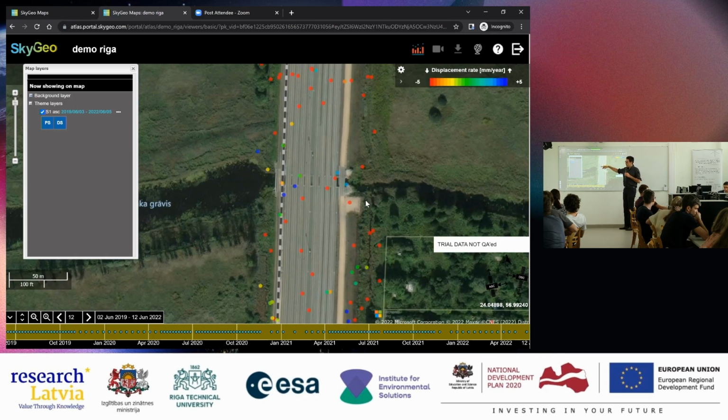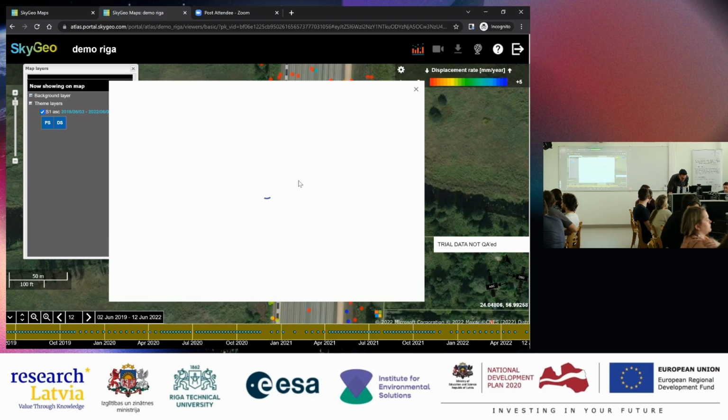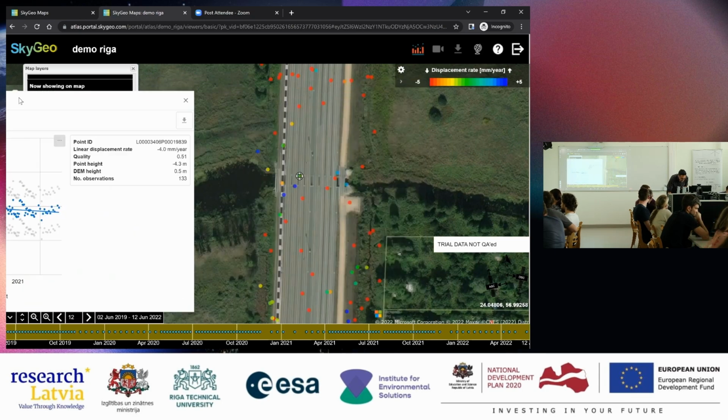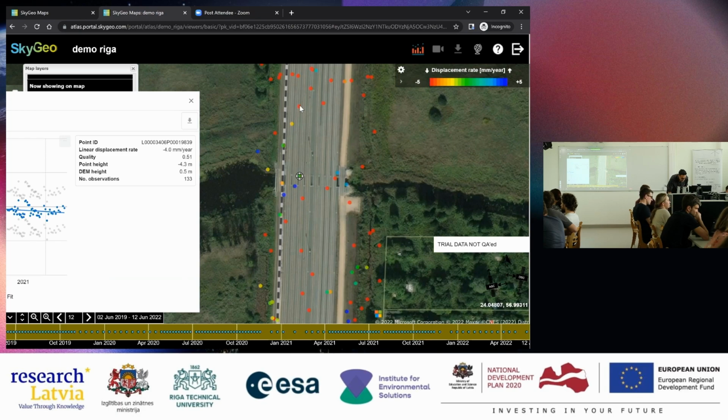Usually, if they build a bridge with a railway or a highway on top of it, then that bridge is a very big concrete structure, so it has to have a very thorough foundation. So the bridge usually is stable because it has a foundation on a lower layer, but the areas next to it not. That is the sandy ballast bed. So the green point over here is probably quite stable. Here, there's an interesting one. Whereas the red points here.